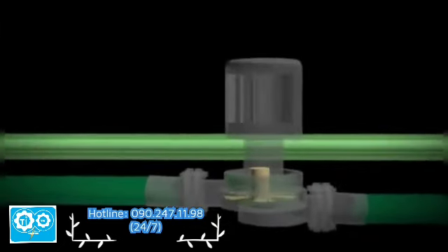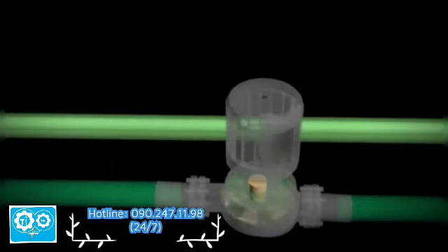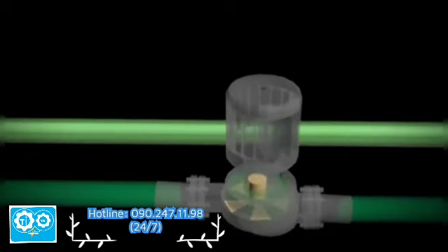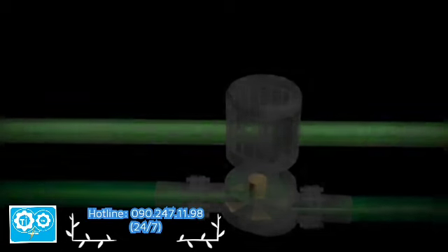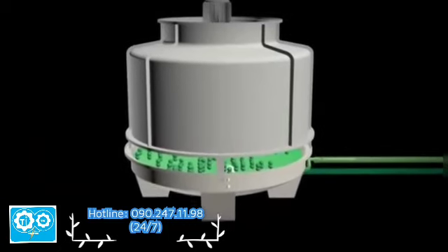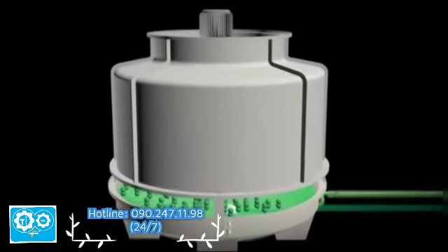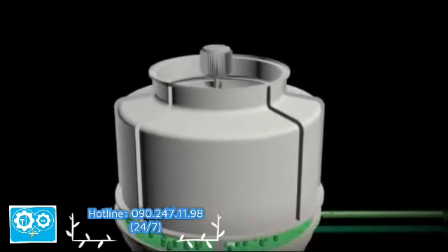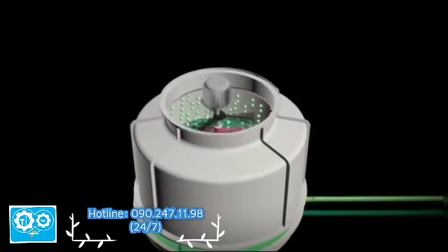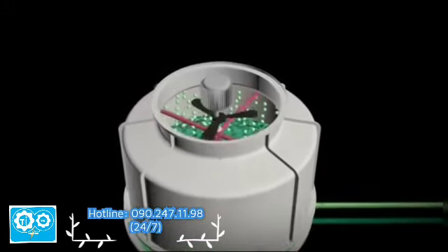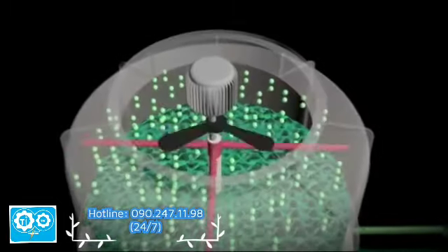From the condenser in the chiller, condenser water flows to the cooling tower with the help of the centrifugal pumps. This water is called condenser water return. This condenser water will pass through the rotating sprinkler blades on the cooling tower. The rotating blades use pressure generated by the condenser water itself.